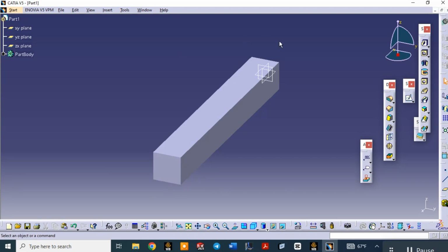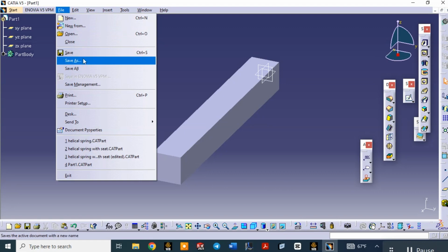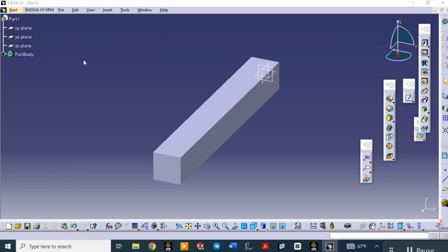One crucial thing that you have to know is that whenever you want to import any geometry to Ansys Workbench which is created in other 3D modeling software, you have to save this 3D object in IGS format. To do that, go to File and click on Save As.